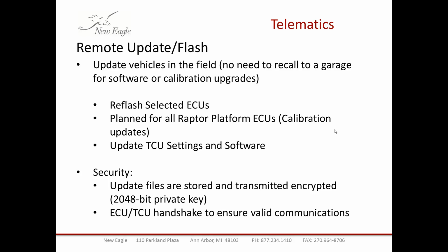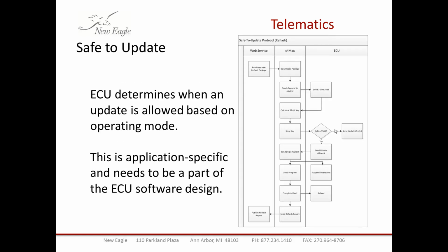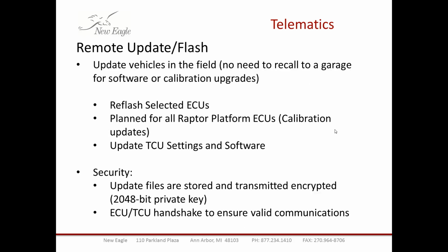In terms of safety, the ECU and the TCU have a handshake to ensure that the update is being applied to the proper device. A part of that is the Safe to Update protocol, which is a CAN-based protocol. Before we get into the Safe to Update too much, remember that when we're reflashing the ECU, the ECU's application is not running.